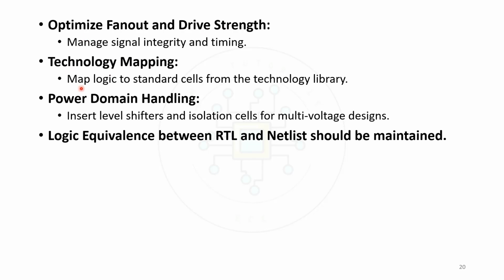Next, coming to technology mapping. Map logic to standard cells from the technology library. So depending upon the technology library that you are providing, mapping will happen during mapping stage. Power domain handling. So insertion of level shifters and isolation cells for multi-voltage design. Suppose if you are working on multi-voltage design, then these cells will get inserted called level shifter cells, isolation cells, and two more are there which are always on cells and retention cells. So finally, logic equivalence between RTL and netlist should be maintained. As I told you, this should be checked by using a tool called Conformal LEC. These are the goals of synthesis.